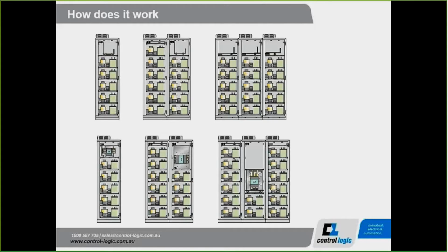What's not shown in this slide, particularly on the front of the cabinet door, is the power factor controller. This is an HMI interface, basically, and it's the brains, the intelligence of the unit. So what we have here is you have to install a CT, a current transformer, and you typically install that on red phase on your supply network. That's wired back into the PFC unit, back to this HMI controller. Also, you have obviously all three phases of the network connected to the PFC unit. It sits in parallel, okay?